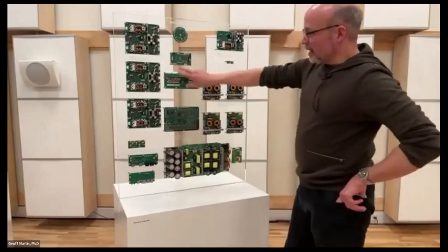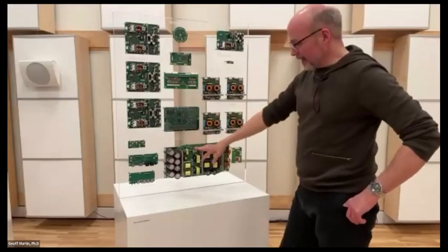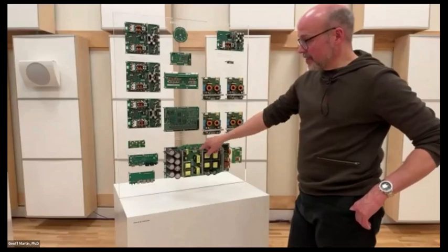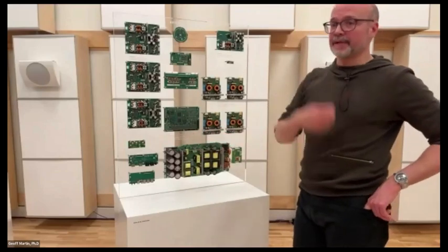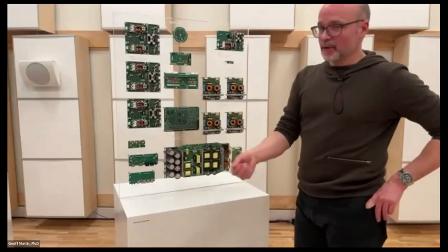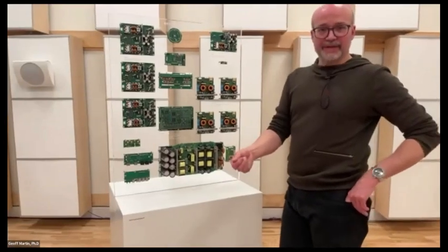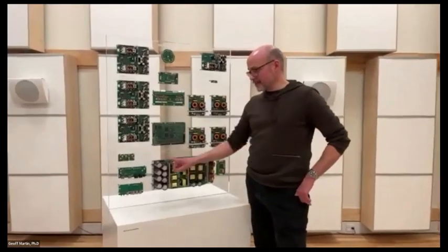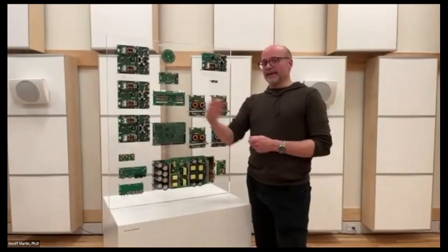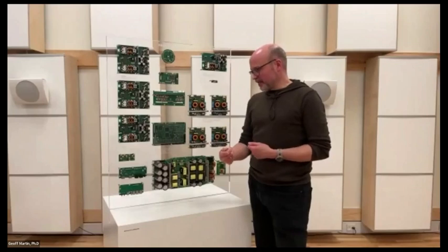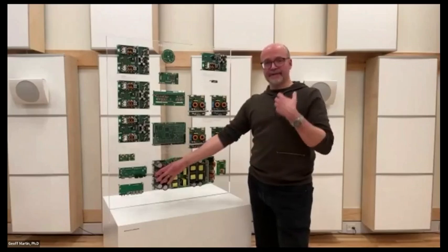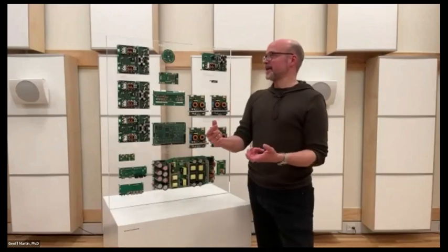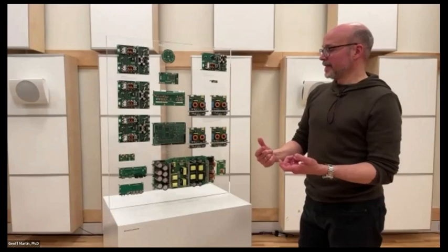That whole thing is being powered by the power supply, which is built in. And this has a microprocessor built on board to make sure that it isn't pulling too much current from somebody who lives, say, in Tokyo, where you have 100 volts at 5 in the afternoon. So the microprocessor is charging up the capacitors, trickle charging, or trickle is a bad word, to make sure that they have the current capability that we need if we have a high spike at a high sound pressure level.